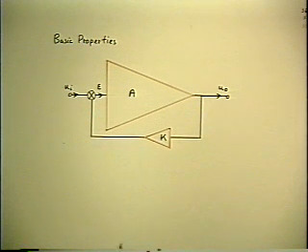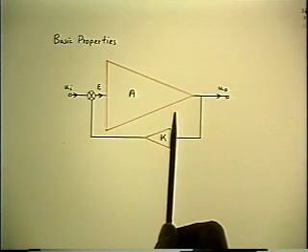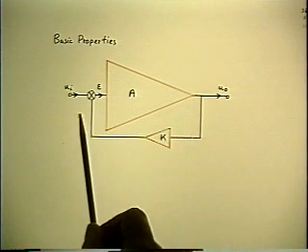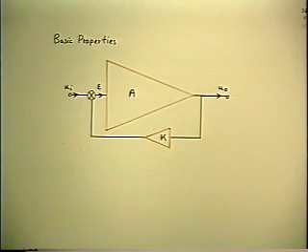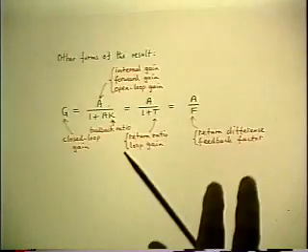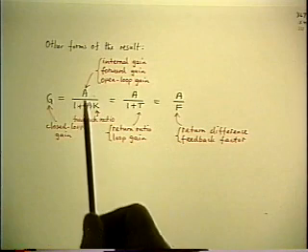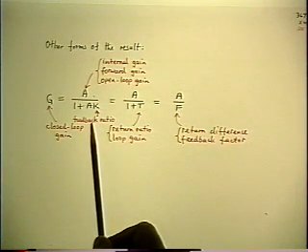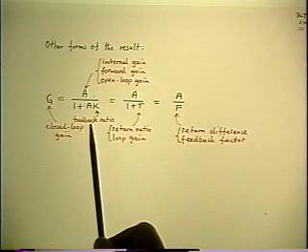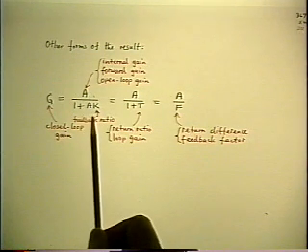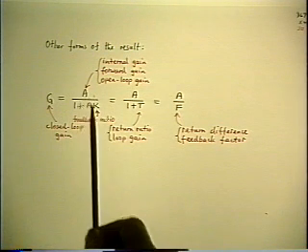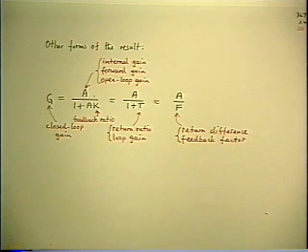But in many electronic circuits, it's not realistic because of interaction between the two boxes at both ends. And so that means that when you represent the closed loop gain in terms of the values of those two boxes, right away you're behind the game, because it's hard to break the loop in such a way as to avoid upsetting the interaction.